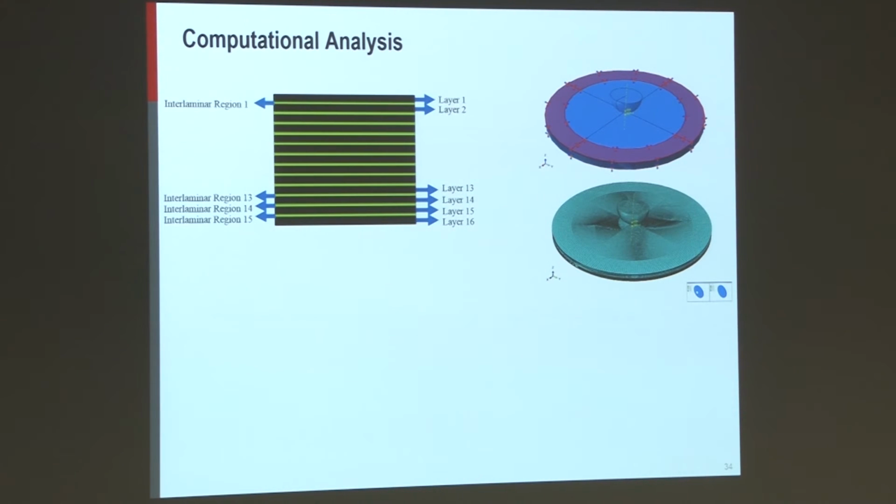Before we could just reinforce all the interfaces in our laminate, we first did a small computational analysis where we created these individual reinforcing layers, about 16 layers, with green regions of interfaces in our model. And we actually simulated the impact test. And this is how it looks.